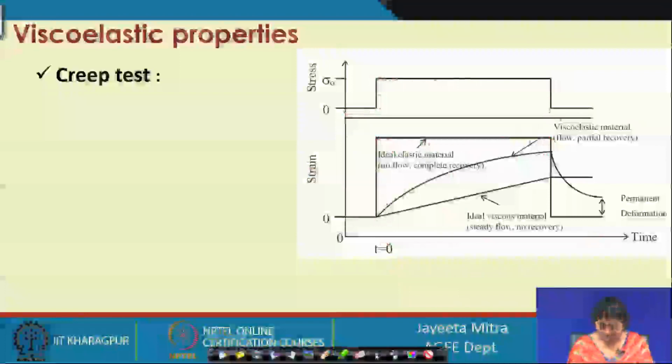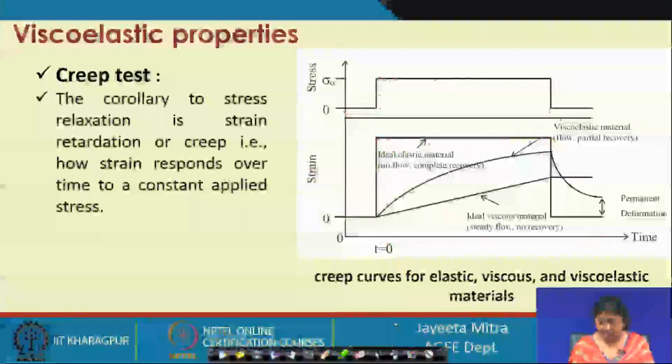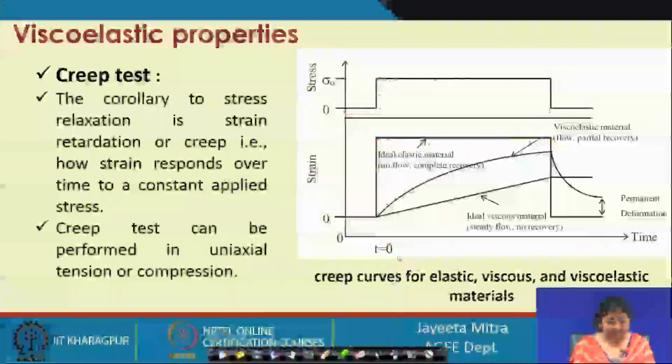We can see the creep behavior for elastic, viscous and viscoelastic material. So, how strain responds over time to a constant applied stress, that is the fundamental of the creep test, and it can be performed in uniaxial tension or compression.